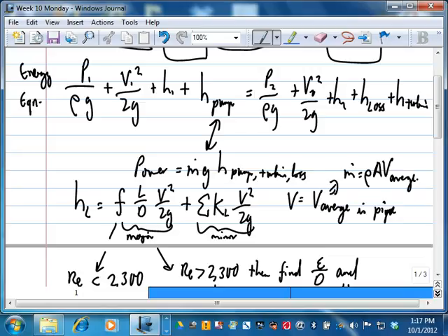It's the number of units of kinetic energy loss when the flow goes through a given fixture. A fixture could be many things. There could be an elbow in the pipe. There could be a valve. There could be entry from the tank into the pipe, or exit from the pipe into the tank. So entry losses, or losses for when the pipe enters the tank, and so on. When a small pipe goes into a big pipe, or a big pipe goes into a small pipe.